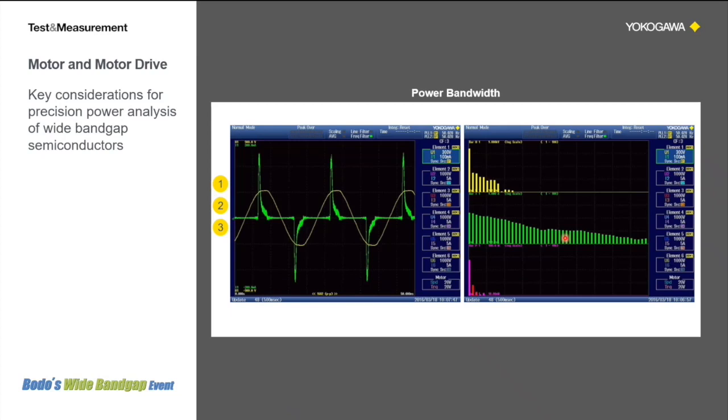However, when there is no voltage and there is current, there cannot be power. We also see that at some harmonic orders there is voltage and current but no power. In this case, there's a 90 degrees phase shift between these signals. However, these still should be evaluated. So the required bandwidth for power measurement is equal to the least distorted signal of the applied voltage and current.